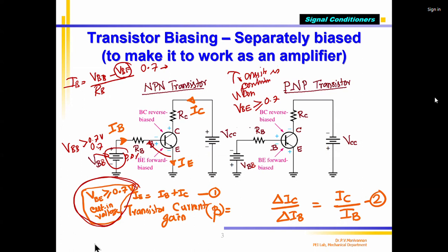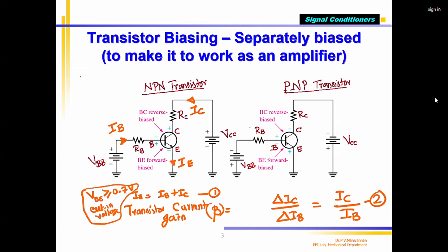So now, if I give 1 volt here, there will be a voltage here. This voltage is called VBE, between the base terminal and the emitter terminal. We have a power supply, one resistor, and the base-emitter junction, which is nothing but a diode. Internally there's a diode there. So there are 3 components: a battery connected to a resistor, connected to a diode.